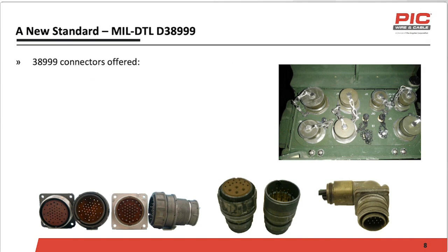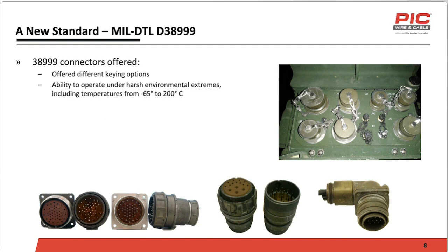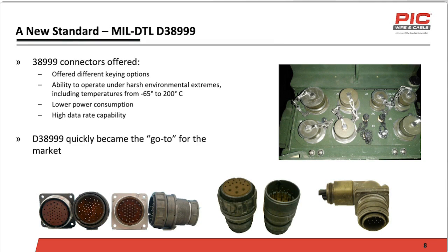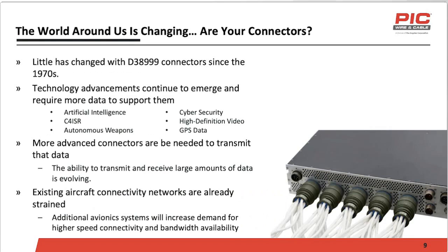These modified connectors now offer multiple keying options, the ability to withstand extreme heat and cold, lower power consumption, higher data transmission rates, and foolproof mating options. Because of these features, the 38999 connectors became the go-to for military and defense applications that regularly rely on interconnects and related components. Since the 1970s, little has changed with the 38999 connectors, but we have seen drastic advancements in